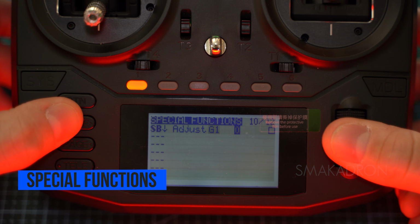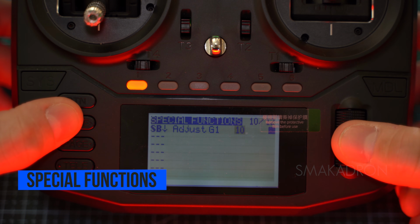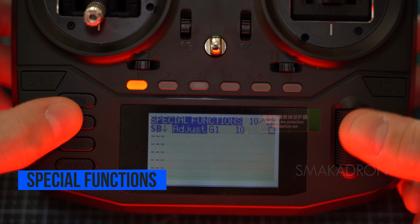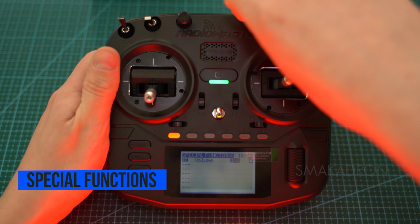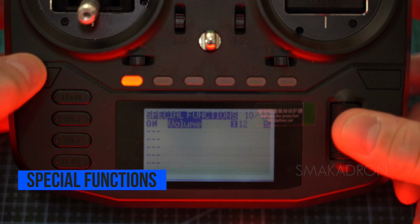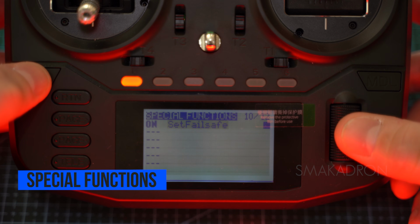This specific parameter currently requires separate testing for FPV drones. It is used by a very limited circle of pilots for their very specific tasks. Volume changes the volume of the radio transmitter. To do this, select the on mode, and I want to assign volume control to a slider. Done. Sets the fail-safe values for the selected module, internal or external, to the current stick positions upon activation.